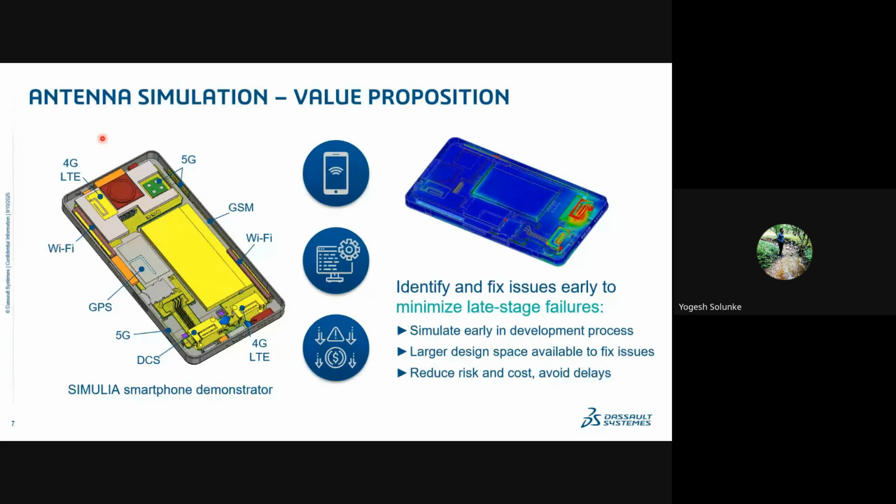Again, taking interference into account, if you see the cameras, all the PCBs and the battery unit, all of these play a very vital role in electromagnetic interference. If it is required, in the case of an array antenna, it leads to an increment in gain. In communication, gain will be increased. But if the interference is unwanted, it degrades the performance of any RF component. So we need to smartly choose the component and its location, where we place it in the casing unit itself.